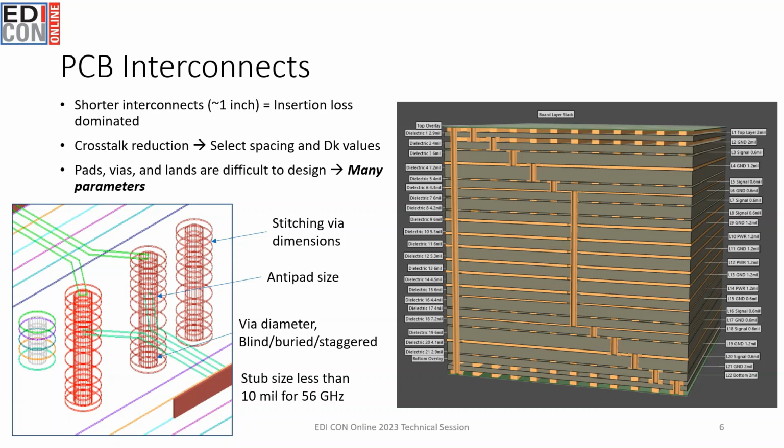So the reason this becomes difficult to work with in the design is because if I start to change one of these parameters in order to achieve minimal loss along these interconnects, it might require me to change at least one other parameter in order to prevent the creation of a new signal integrity problem at a different frequency. This is one of the reasons that we rely so heavily on simulation in designing these interconnects.